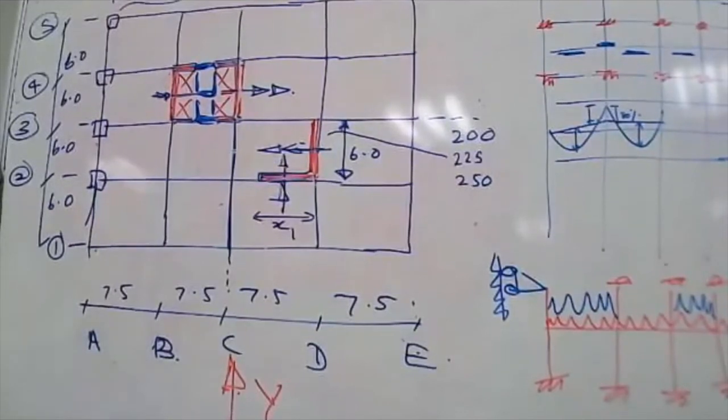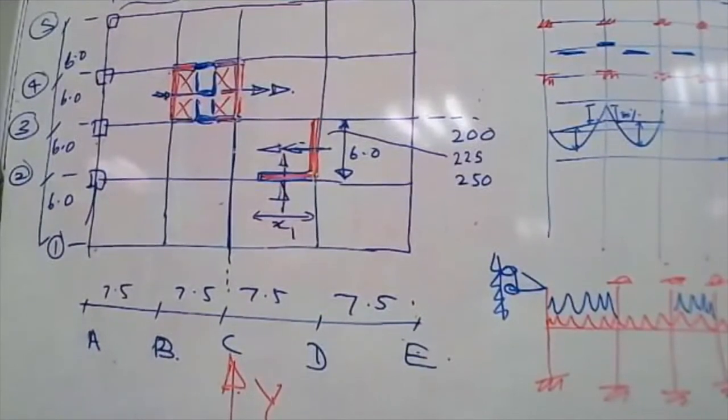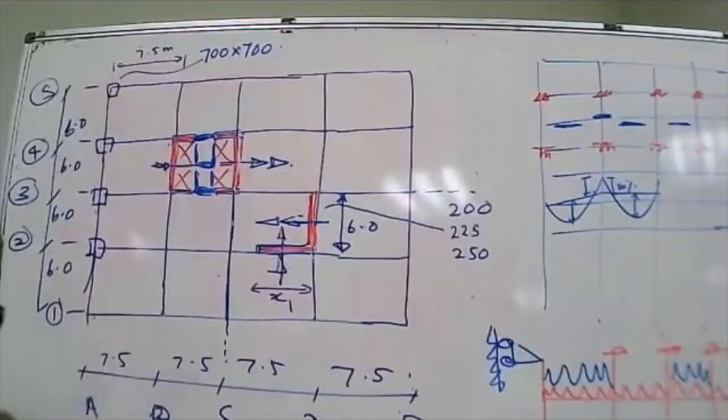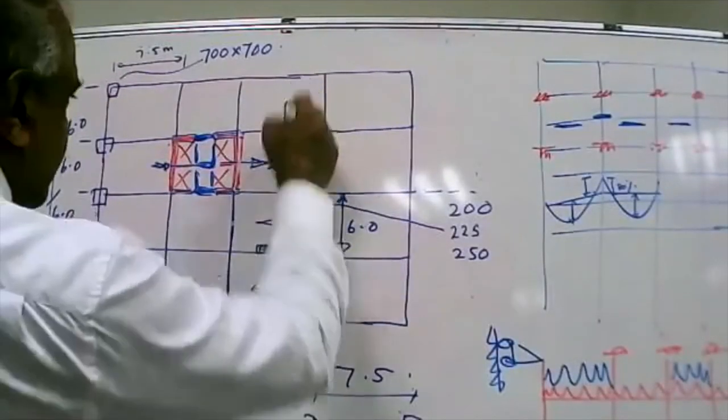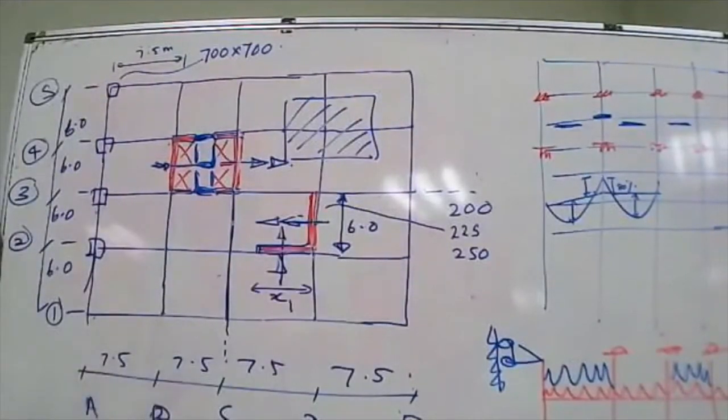Based on that, you can do a quick manual calculation and find the maximum load at the base level. Because you can always find the load that is transferred onto a column by the beams when you do the subframe analysis, based on that you can make an estimate of the column load. Otherwise, you can go for the tributary area and do the calculation. That is also possible.